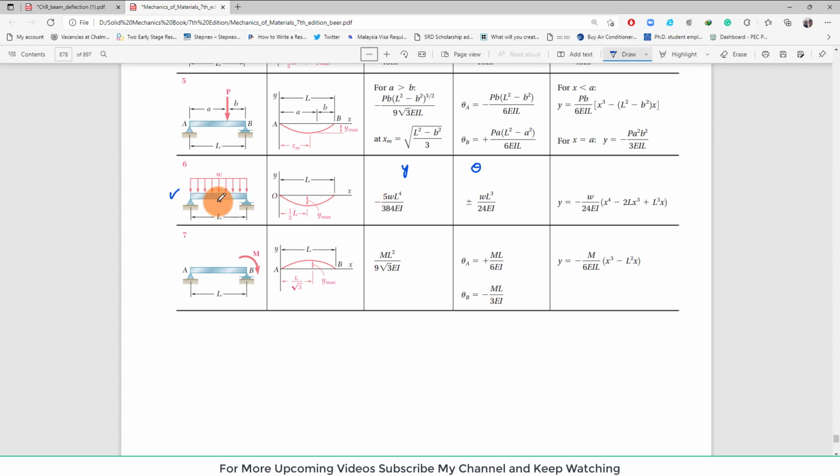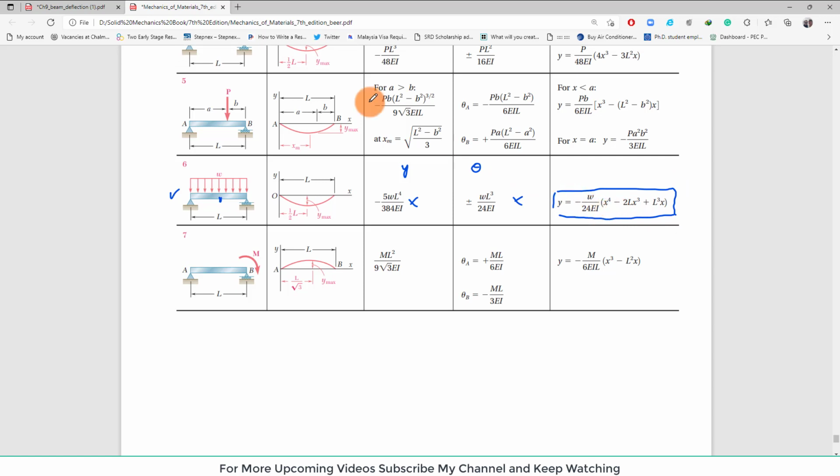So we are not interested in the deflection at the middle point, so we cannot use this deflection as well as slope equation, clear. So what we will do is that we have the equation of elastic curve, so we will use this equation in order to find the deflection at any point X.